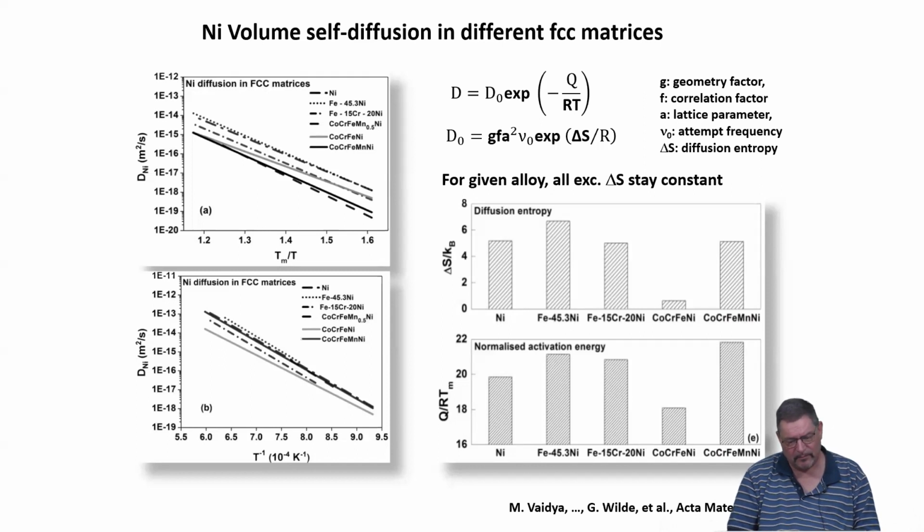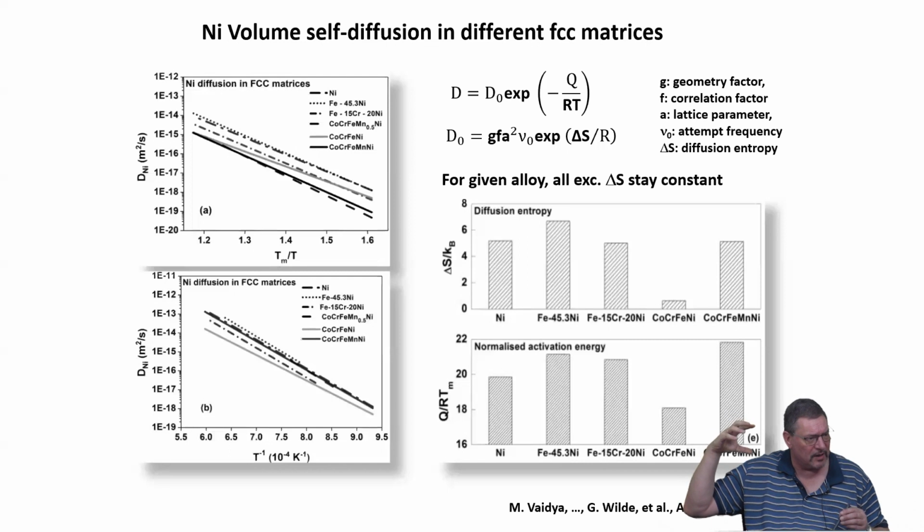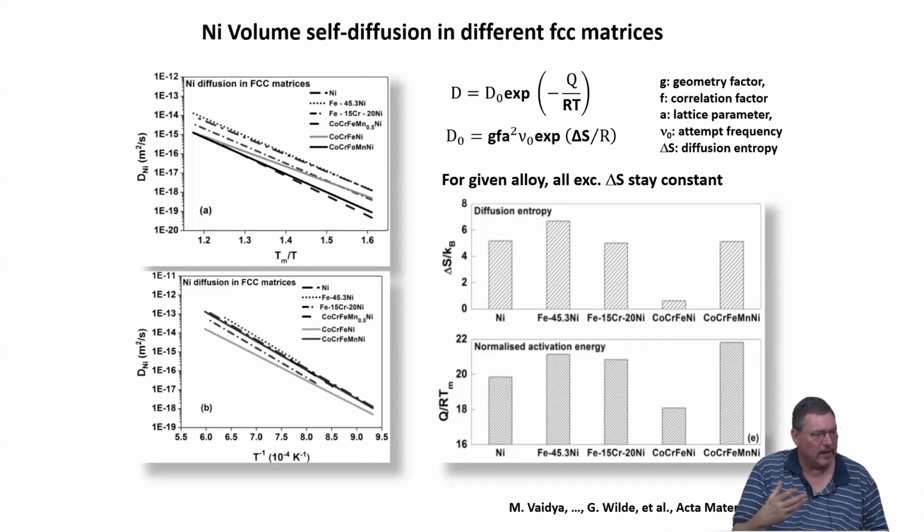So, as I also indicated, there's also always the additional comparison one has to have in the back of the mind, that you have to compare it to the expectations just coming from normal alloying if you go from a binary to a ternary, let's say, right? And so this is, I think, really a nice confirmation that just stating diffusion in high entropy alloys is sluggish is at least very questionable.